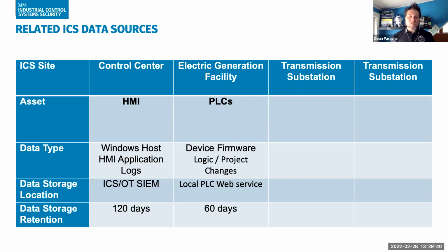case. Yes, PLCs do tend to have, more so now than before, web access interfaces. You can actually do a web HTTPS into a PLC to get its status information and also get the data logs, right? The security logs. So it may have that capability, it may not have that capability. And remember, when you're doing your threat hunting, executing it from a physical location may limit you to the data you're going to get. This again may require you to get to a specific site, which is awesome. I totally recommend getting to the site for threat hunts for the other benefits we talked about before.